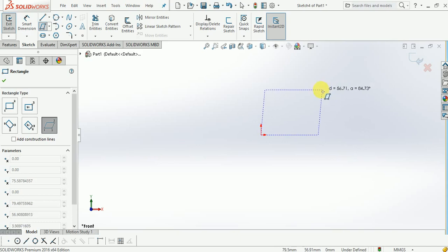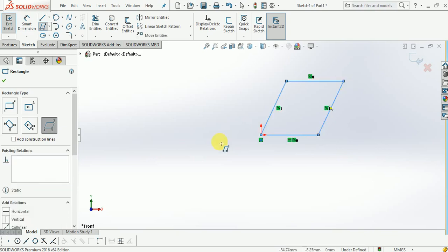That means the difference between the above four and this one is that the above four default to a 90-degree angle always. Whenever you go to the second point and jump up or down, it makes a 90-degree angle. But this one is not the same, since it's specified as the parallelogram for the rectangles. So if I move this way, I make a parallelogram with an angle of 63.55 degrees. I click up here, and then it's created.